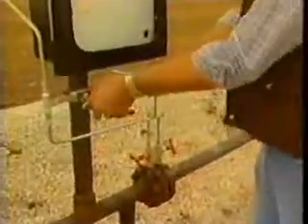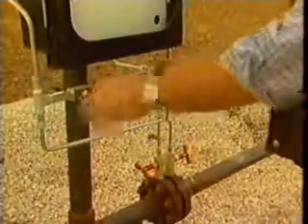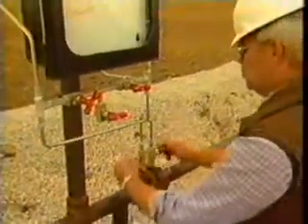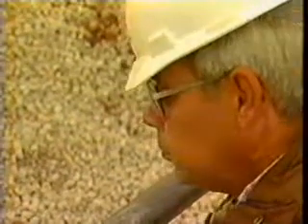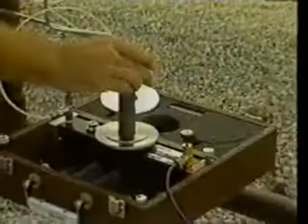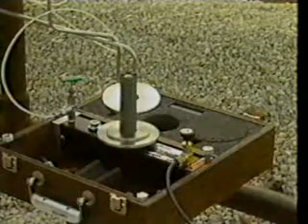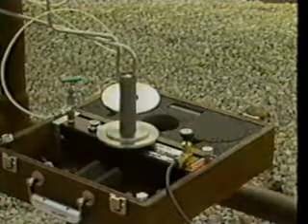Now take the density readings and samples before taking the flow recorder out of service. Always remember to take the meter out of service and be sure to inform the proper personnel. Check for piping leaks. Check the differential element for calibration at a minimum of 5 points, both up and down the scale. See that the inking pens have the proper pressure against the chart, that the pens are in good condition, and the ink flows properly.